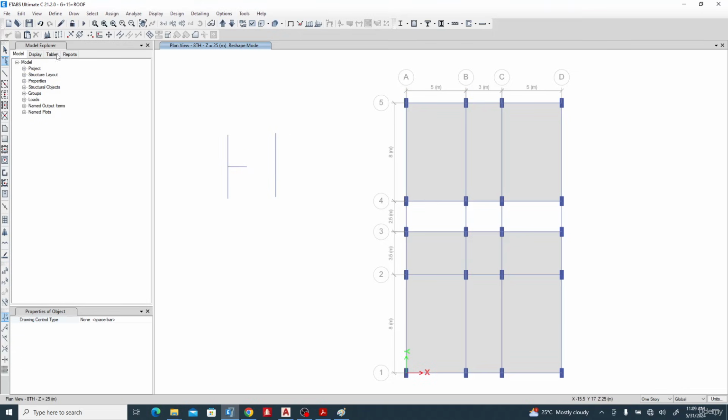So this is what we have. I can select my beam, and I want to extend it to the face of this place. So what I do is select this joint and select this beam. Let me join this back. So select this and join. You can see join here, join frame. So it's now one.